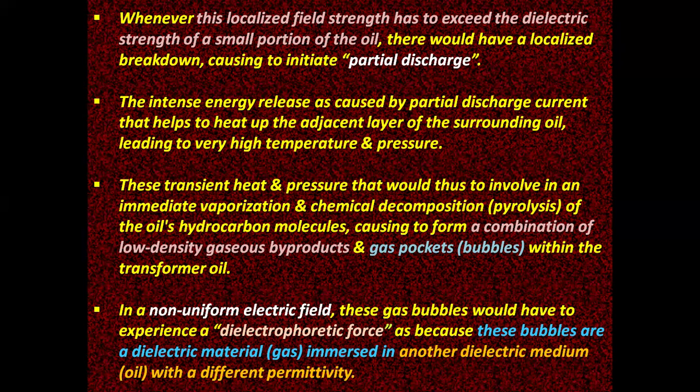This transient heat and pressure involves an immediate vaporization and chemical decomposition, that is pyrolysis, of the oil's hydrocarbon molecules, forming a combination of low density gas byproducts and gas pockets, that is bubbles, within the transformer oil.